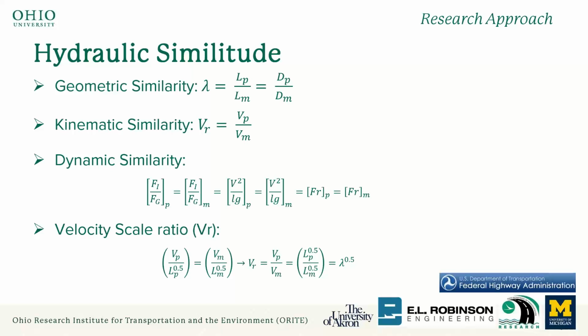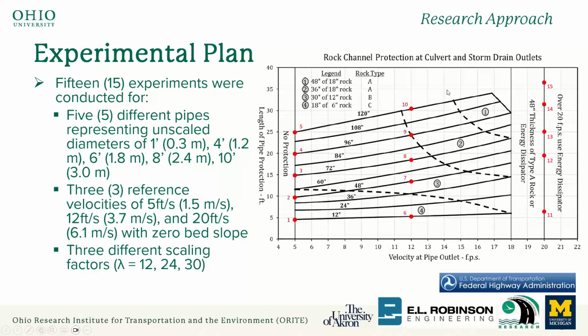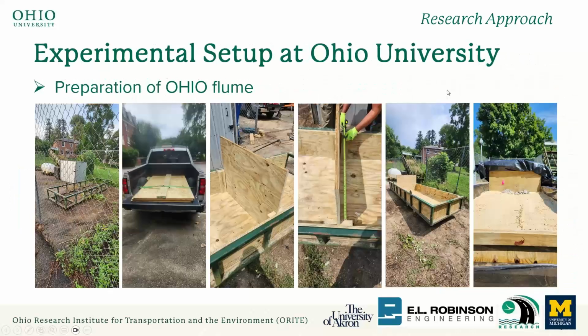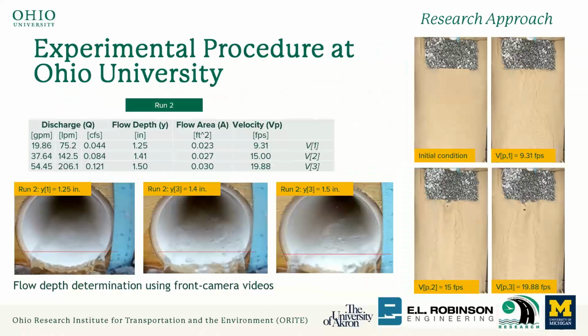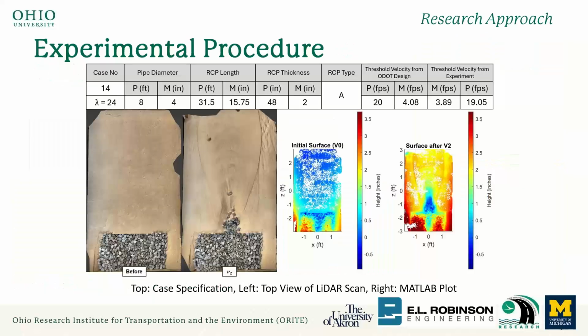Yeah, that's a good question. Since we don't know what the ODOT chart is based on, it's hard for us to really answer any why questions based upon it. In general, what we do know is that, as Danny said, the saturated conditions experience a lower effective stress, so the sand is easier to scour.